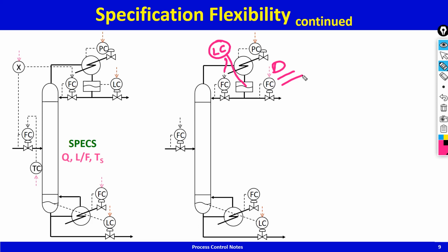What I'm doing here is I'm basically recirculating the material back into the column. And if I recirculate the material back into the column, the only way of adjusting the feed is to adjust the tray temperature by manipulating the feed. However, the tray temperature response to liquid flowing down is going to be very slow, and let's say I'm controlling a stripping tray temperature as usual.